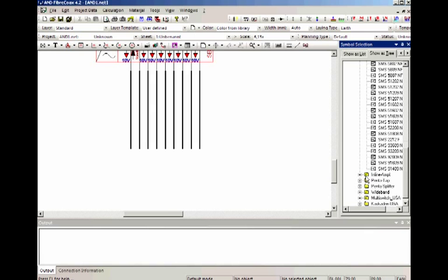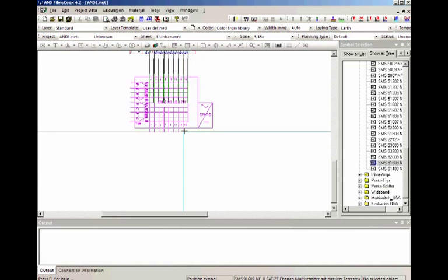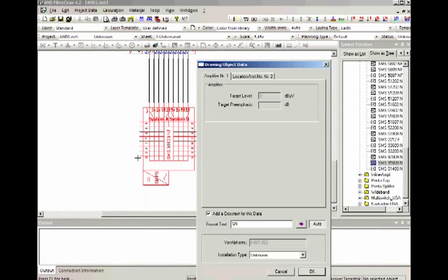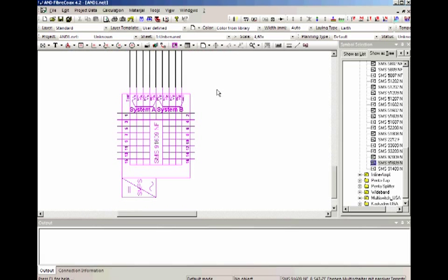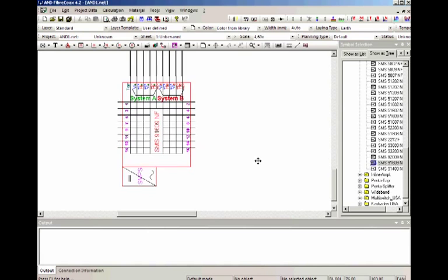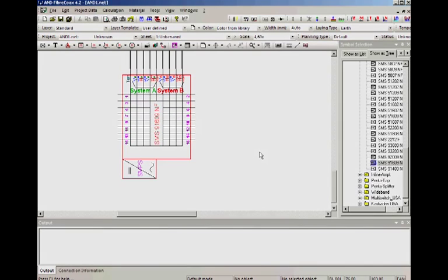So I'm just gonna take one from the library, place it here, and you can see it has 9 inputs, 8 for the 2 LNBs and 1 for the terrestrial antenna, and 16 outputs for customer outlets. Next step is to connect these to the customer outlets.